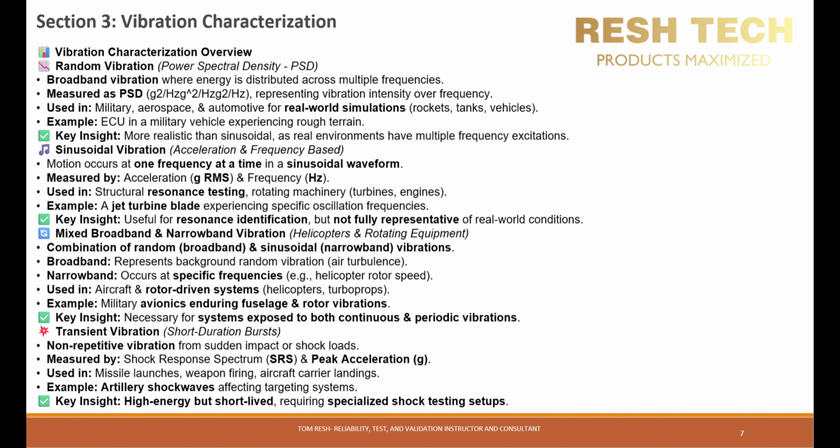A key consideration is that random vibration is more representative of real-world conditions than sinusoidal vibration because most operational environments contain multiple frequency excitations simultaneously.